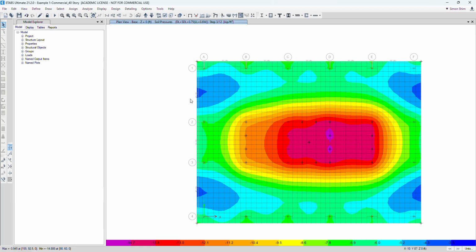So I want you to just test it, set it up, and include it in your foundation design. This is a kind of first sizing check, to see whether all the stress based upon the ASD method is under our design allowable bearing capacity.